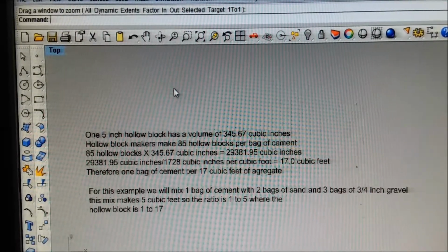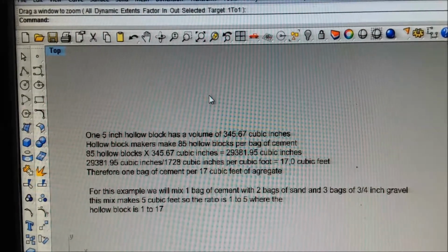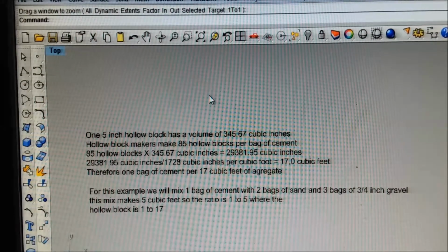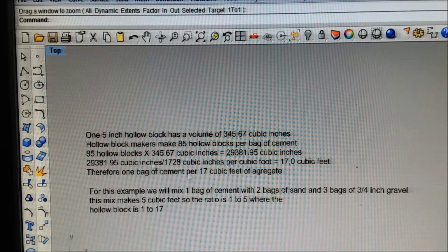Early on, we were measuring water in 5-gallon buckets, 4 gallons of paint in a 5-gallon bucket. That's what they sell. And we were trying to get equal weight of cement to water. And we found out that we had to add about another quart to that for a 1 bag mix. And it doesn't pour awful easy. You have to shake it with a rod or a vibrator or something to compact it. But if you put too much water, you lose a lot of strength.